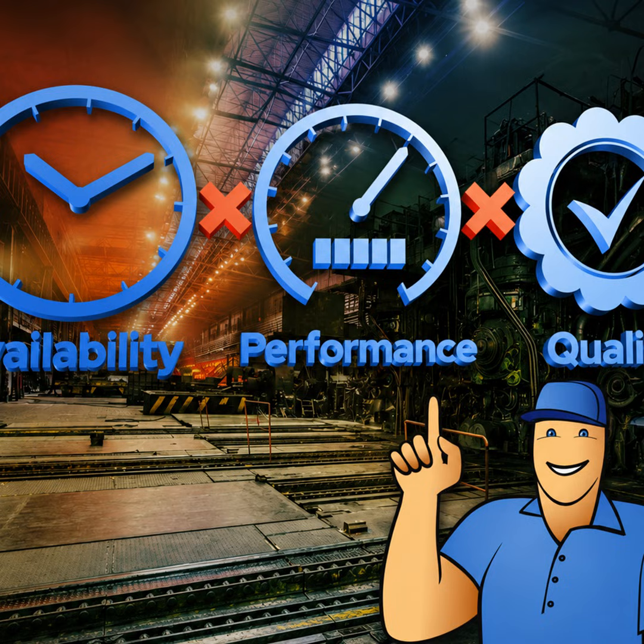Regardless of your starting point, do these first. Get honest baseline data before anything else. Track OEE consistently for at least 2 weeks. You need your true starting point, not your best day or gut feeling. Identify your top 3 losses by category. Is availability killing you? Performance? Quality? Pick the pillar with the most opportunity and focus there first.